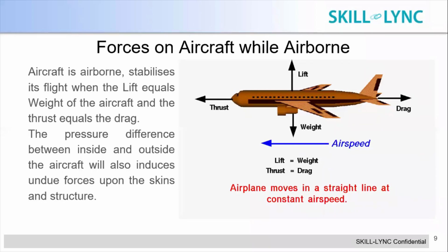So there is one atmospheric pressure inside your capsule, I mean the aircraft fuselage, inside the passenger chamber, whereas there is an entirely different pressure outside the aeroplane or aircraft. So there is a huge pressure difference subjected on the entire capsule and aeroplane. Even that induces a lot of forces, where the design of the structure gets more critical to take up all these loads.